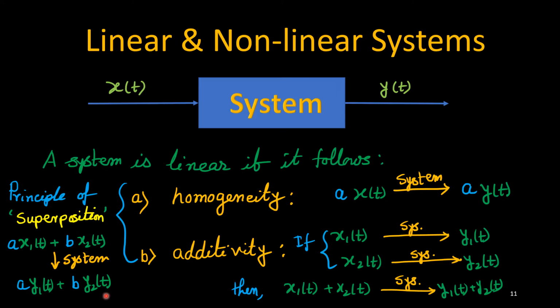And you have seen that in circuit theory, this RLC network, the resistor, inductor, and capacitor network, is always a linear system. And in that linear system, the superposition principle is applied. So in the circuit, if you have more than one signal, you can consider one signal at a time, then you can find the corresponding output. And next time, you consider another signal, keeping other signals 0. Then again you will get the output signal. Then at the end, when both signals are present, the output will be the addition of those two previous outputs. So that kind of superposition principle is used in linear systems.